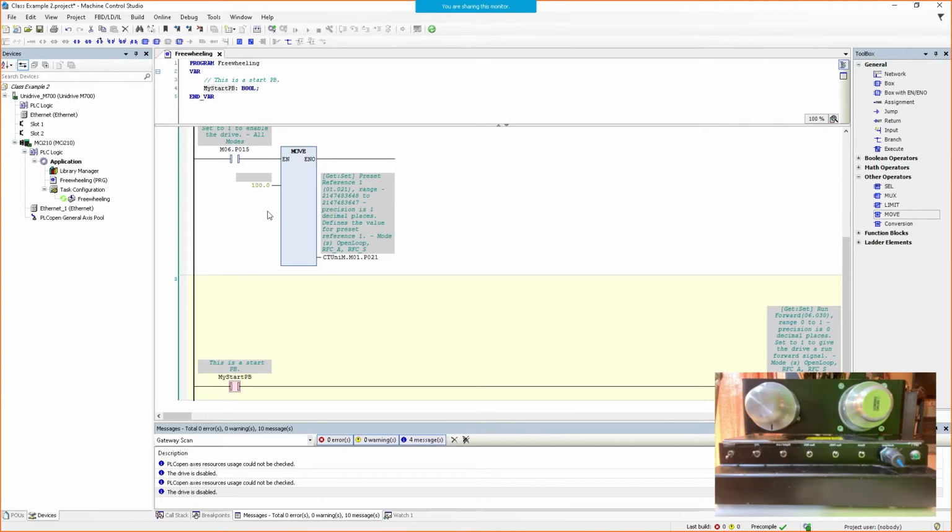What I also would like to show you at this point is I am going to replace this constant with a user variable. Instead of writing a constant, which isn't very practical, I'm going to click there and change this to read user speed instead.